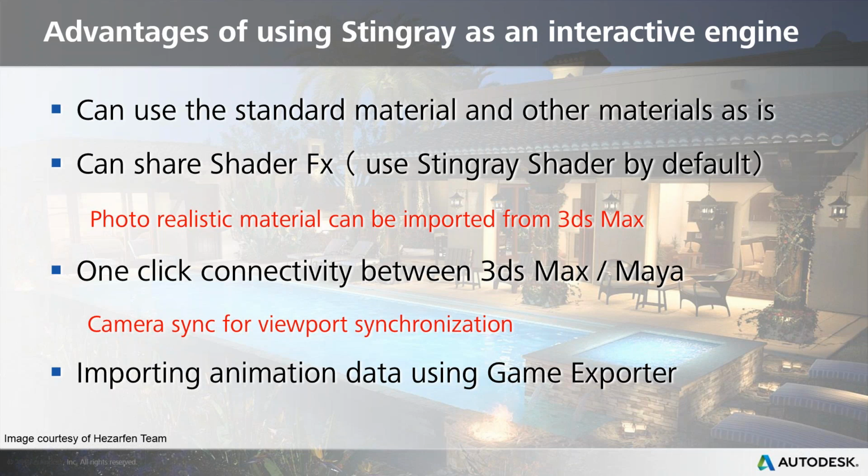The reason it's called a game exporter is that if you're talking about any kind of walk cycles for a person walking around, you can have the game exporter export these as different clips, like a walking clip, running clip, jumping clip. That's what the game exporter helps with. And if you want to export a camera animation, that is also possible, because then it will be just the keyframes of that camera which get exported.